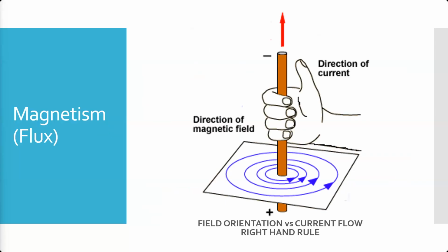Now, for our purpose, we don't really care which direction it's going. In fact, we're going to be using AC, alternating current, mag particle equipment, and so ours is going to flop 60 times a second, because the electricity running in the US power grid is 60 hertz. If you do this in Europe, it'll flop 50 times a second. At the end of the day, that doesn't really matter to us much. We aren't too worried about which way the field ends up being. If I let go of the button that sends current through the part, at this fraction of a second, it may be oriented one way. If I hold it 1/60th of a second longer, it'll be oriented the opposite direction. It doesn't really matter, but the part's magnetized at that point.